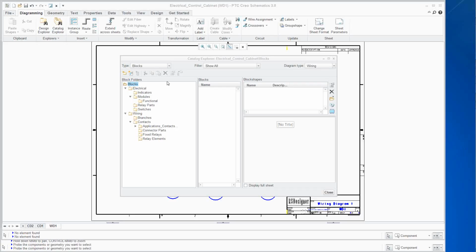So another thing is creating and renaming folders in a single operation. Depending on what type you want here, a block or a port, you can create a new folder. Notice the folder parameter dialog box allows you to create a new name for that folder. Once you select OK, it'll automatically create that for you with that name. So before, that was two operations.